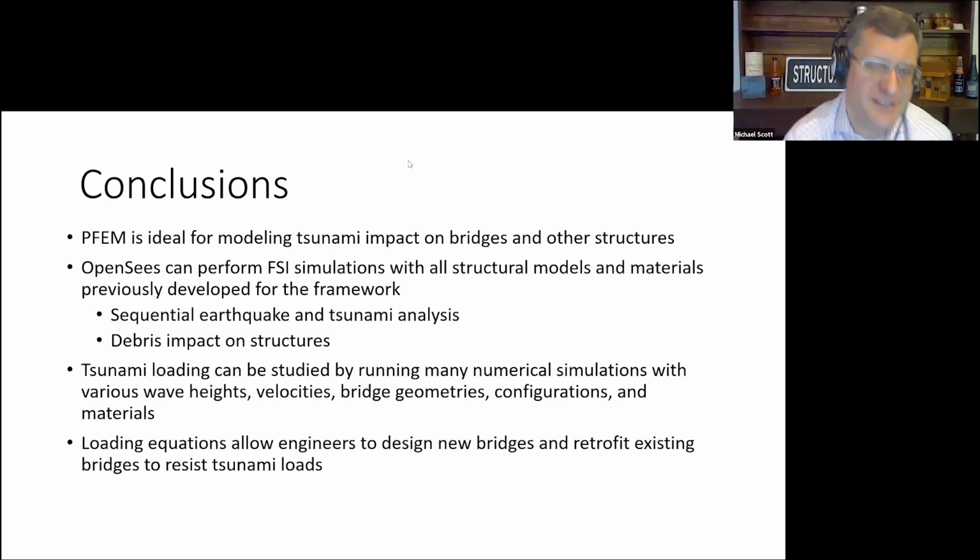Yes, most definitely. So you can, like anything, I assume you're familiar with OpenSees, Jonas, but like the fiber sections or nonlinear or force-based beam column, displacement-based, all of those models can be used within a PFEM analysis. So you can do RC buildings, either to do an earthquake and then a tsunami, or just do tsunami loading on these types of composite structures. It's not a problem, so to speak, it's all kind of there in one package. It's not a separate thing from the rest of OpenSees.